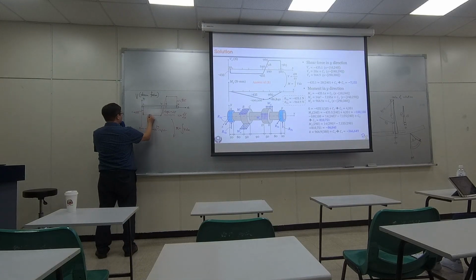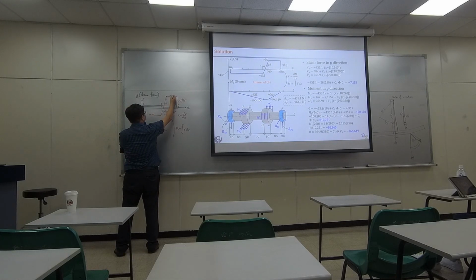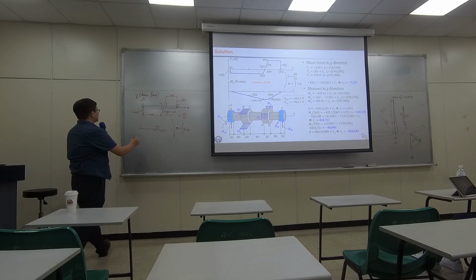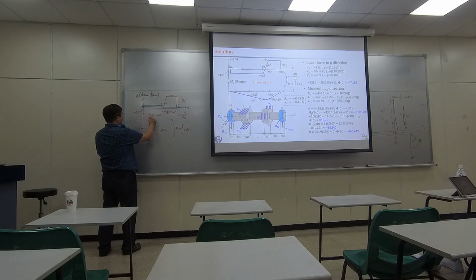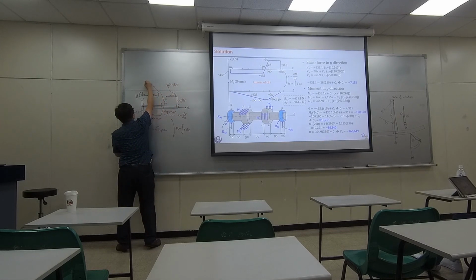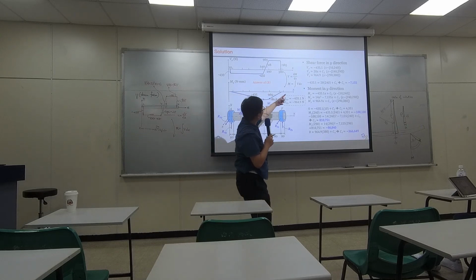This value right here is negative 435. This value here is positive 965. Okay? And in fact, you can formulate equations right here. This is V(x) equals negative 435. Here is V(x) equals 965. How about this guy? This is actually V(x), the slope is 28x, plus a constant. I can call it C1. I did the same thing here, C1.